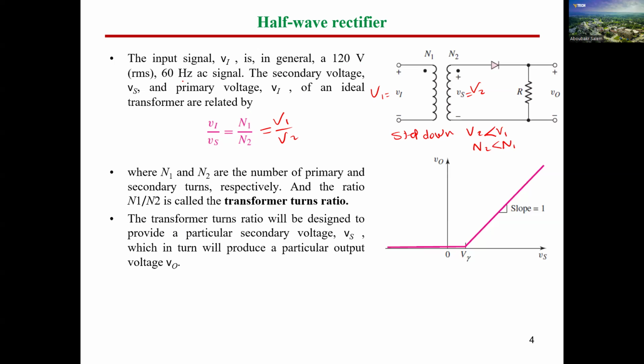Actually, guys, this depends on where your place is relative to the main transformer. All of these voltages, 110 is correct, 120 is correct, 115 is correct. But if you have a transformer very close to a house and you don't have a lot of loads on the circuit, this means the voltage drop across the cables in the street will be less.